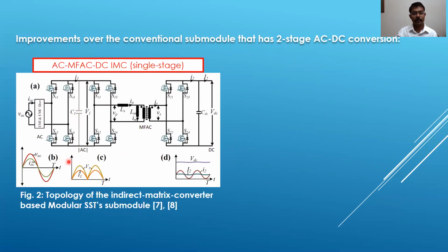And the second harmonic ripple is being transferred towards the back end, and the interleaved operation of the 3-phase modules would then cancel the second harmonic ripple, as the second harmonic ripple from the three different phases are at 120-degree phase shift, and they get added up to get cancelled. And as a result of the control, you would have a very nice sinusoidal current at the grid side.